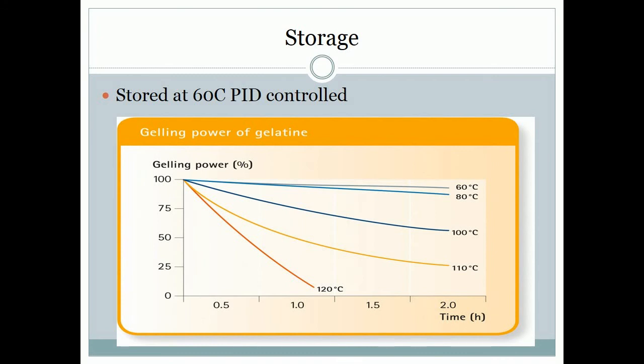So the only thing left to consider is the transportation from storage to the rollers that press the gelatin into a solid sheet. And for this the best solution is to use some heating tape to keep the gelatin liquid during transportation. In transportation you want a small distance between the holding tank and the rollers. Usually the storage vessel is at a higher elevation and most likely situated on the floor above the rollers.